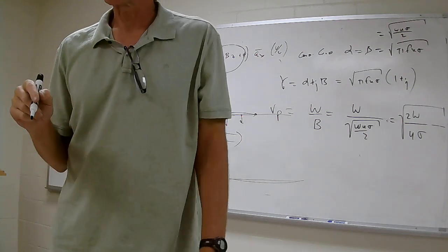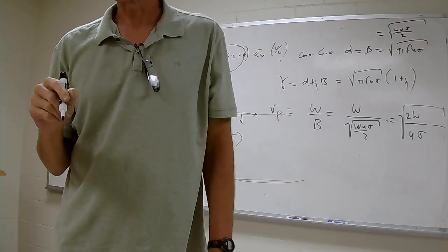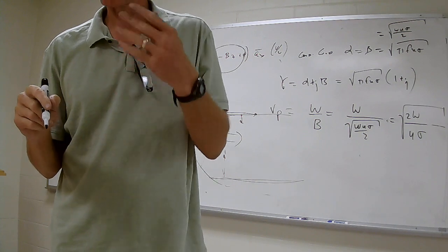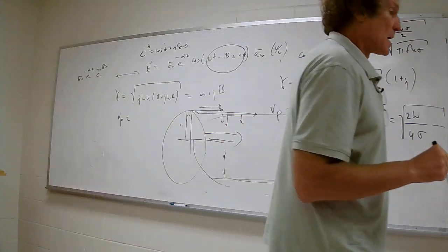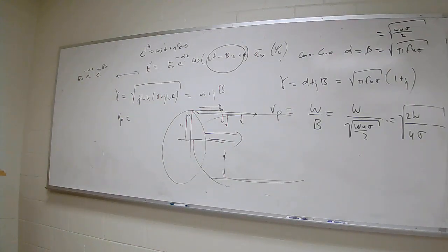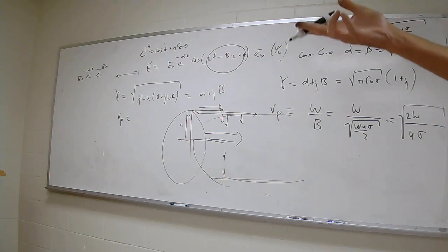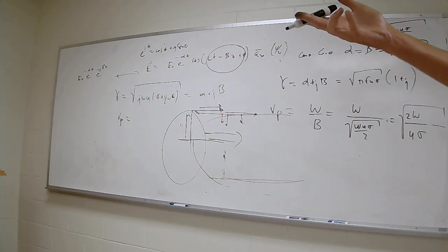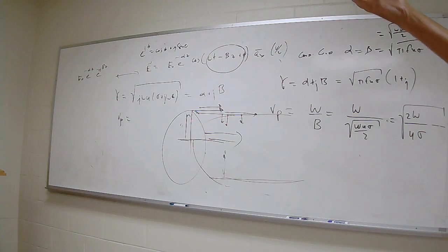Do you know the definition of a phasor? The way we did it? In circuits, do you remember how they do it? They assume that the electromagnetic event, voltage or current, is going to be e to the j omega t, plus a phase angle. So they write the differential equations, and lo and behold, on both sides, e to the j omega t appears. So they cancel it. Then they say, we know omega, so now we're talking about phasor voltages: magnitude, angle, magnitude, angle.